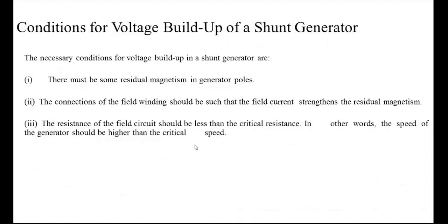Third, the field winding resistance. The resistance of the field circuit must always be less than the critical field resistance. That is another condition for voltage buildup. If it is larger than the critical field resistance, it cannot produce voltage.